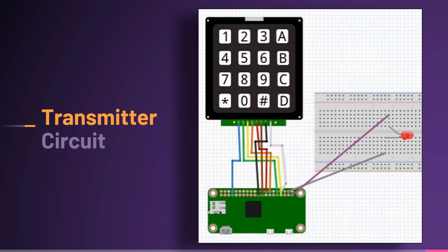The information is then handled by the control unit, which in our case is a Raspberry Pi that is programmed using the C language. The Raspberry Pi transforms the data into binary bytes that can be transmitted using an LED source. The data is then fed to an LED lamp, which emits visible light pulses to the receiver. In addition, each input and output pin in this circuit is determined in the C code for the programming.